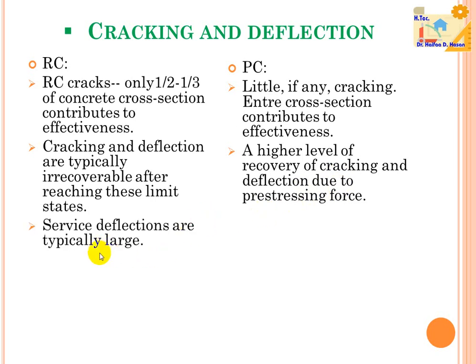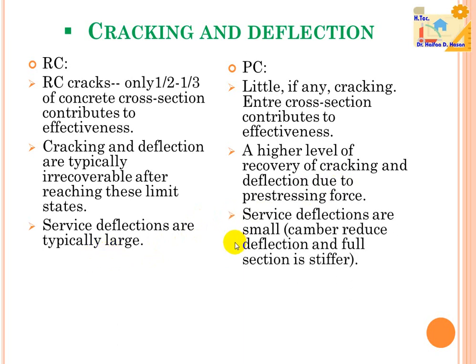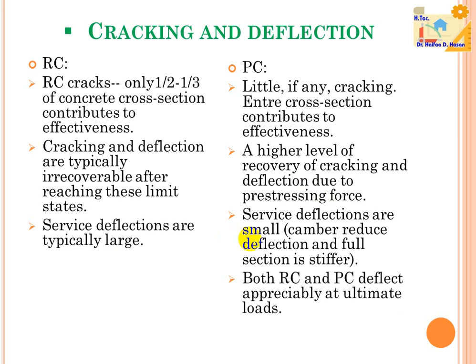In reinforced concrete, service deflections are typically large, while in pre-stressed concrete, service deflections are small, with camber, reduced deflection, and a stiffer full section. Both reinforced concrete and pre-stressed concrete deflect appreciably at ultimate loads.